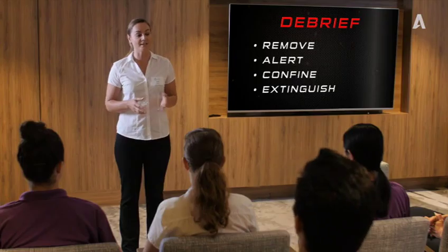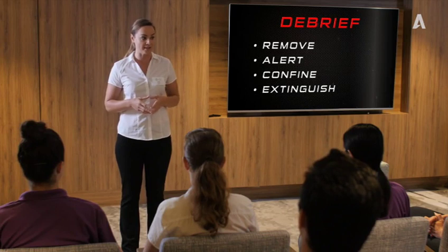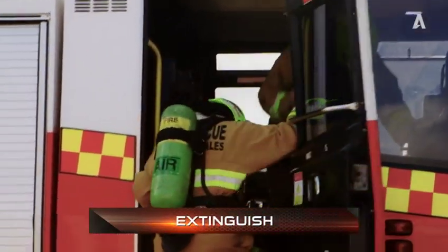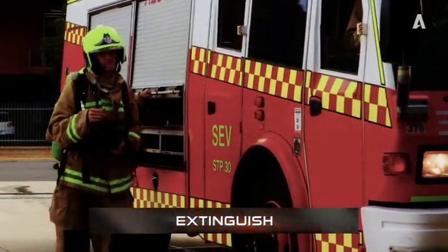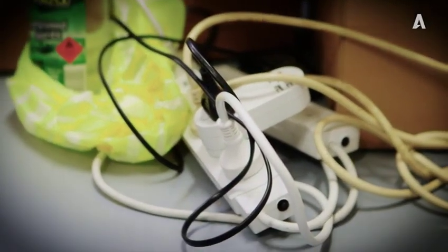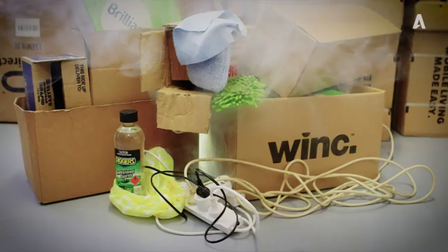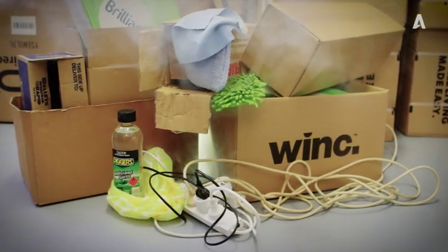You decided to contain the fire behind the storeroom door and waited for rescue services to extinguish it upon their arrival. The fire rescue investigators tell us the fire came from a spark between an extension lead and an overloaded power board. The connection was resting on a rag that still contained a flammable cleaning chemical residue, and a spark from the bad connection led to a fire starting. Nearby cardboard boxes quickly increased the size of the fire.